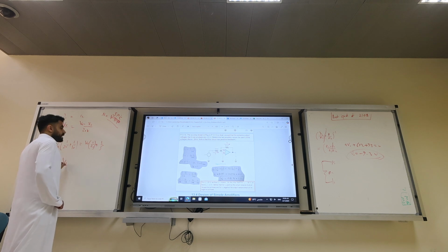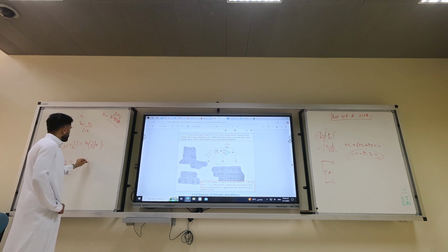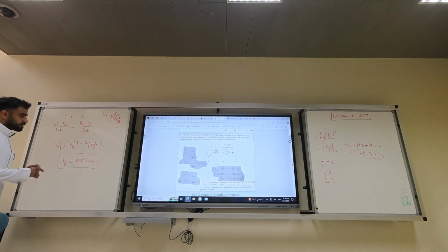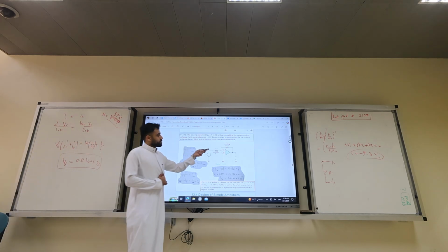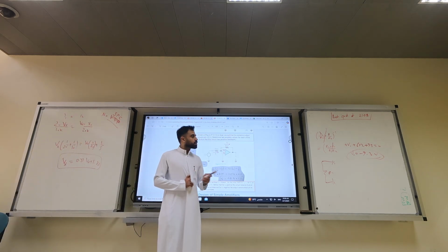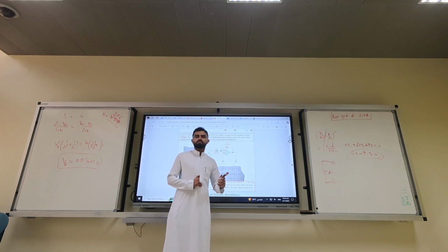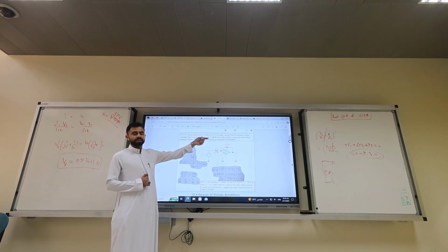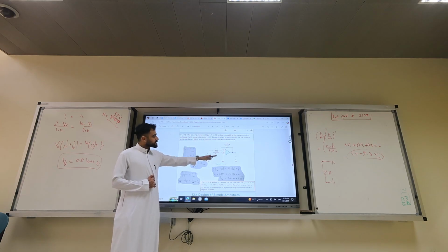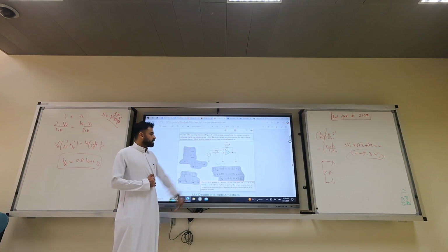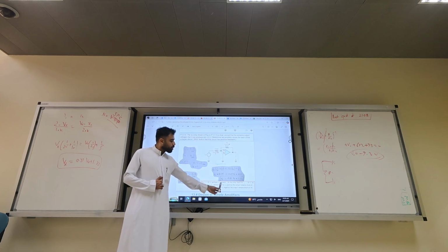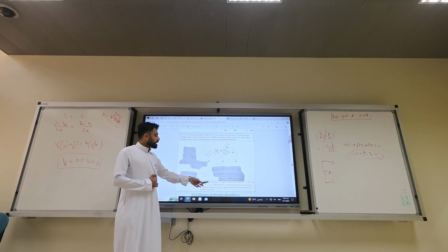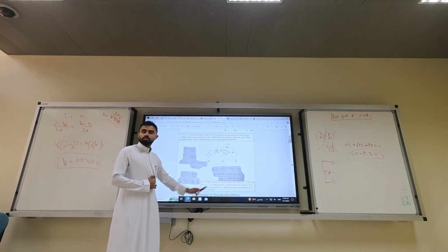So basically you will have Vx equals 0.33 V output plus 1.33. Now, what does that mean? You already put 2 volts. So always you will have an output either plus 10 or minus 10, regardless. The supply here is plus 10 and minus 10. What's going to change is Vx. If you have 10 volt, Vx will be 4.66. If you have minus 10, Vx will be minus 2.